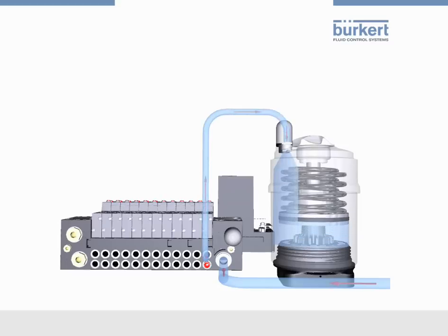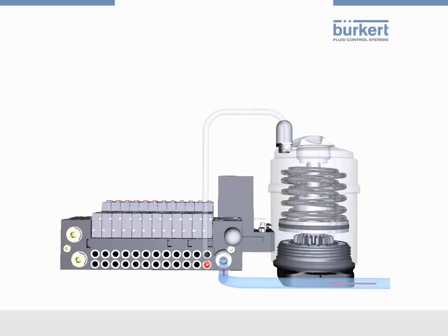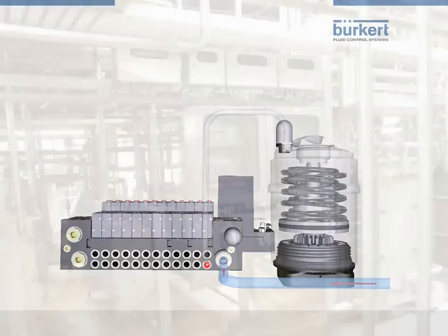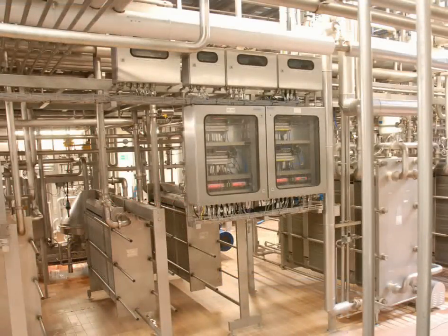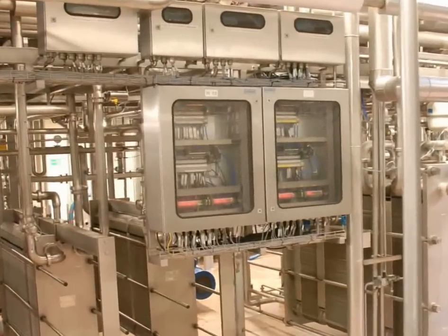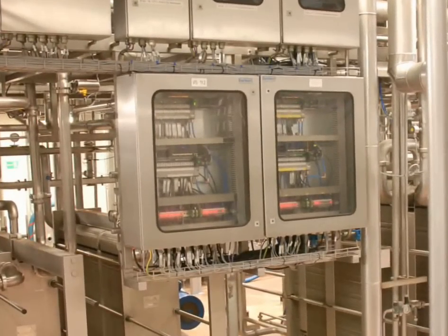When the pneumatic valve switches off, no compressed air flows in the actuator. There, the piston returns to the initial state by the power of the spring, and the exhaust air in the actuator is vented via the valve island to the atmosphere. The function shown here could be used, for example, in a dairy. The valve island is mounted in a control cabinet, and the process valves operating the plant process the milk from one production step to the next.